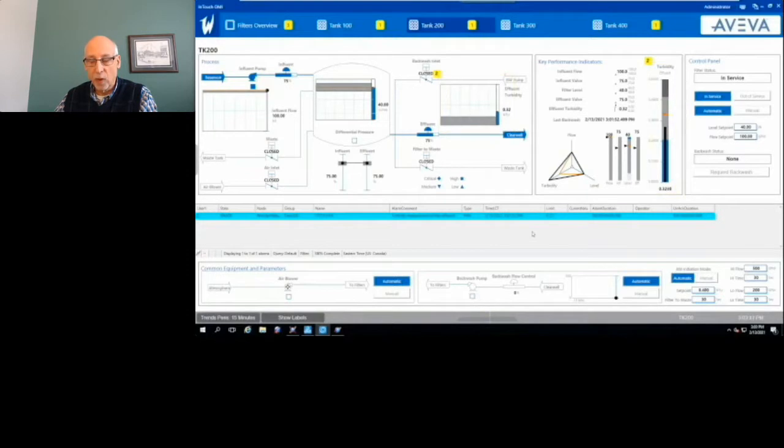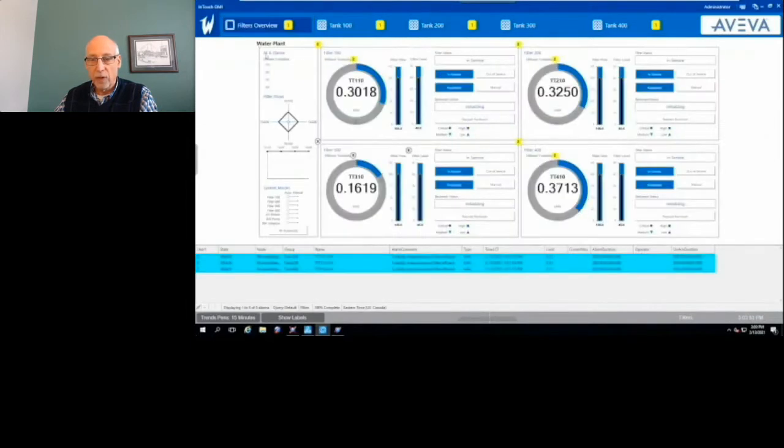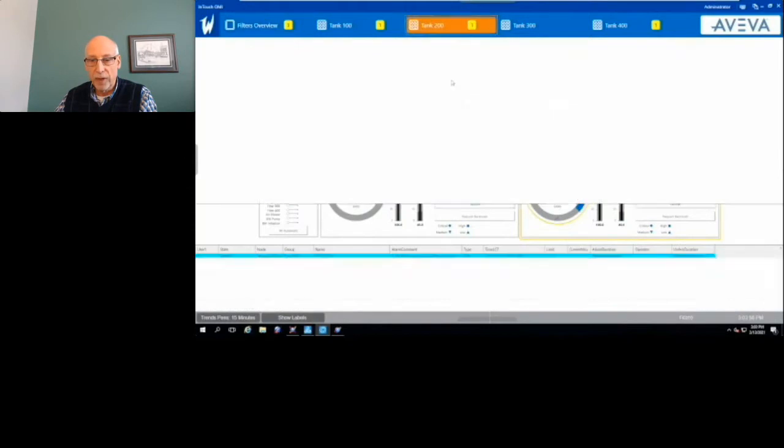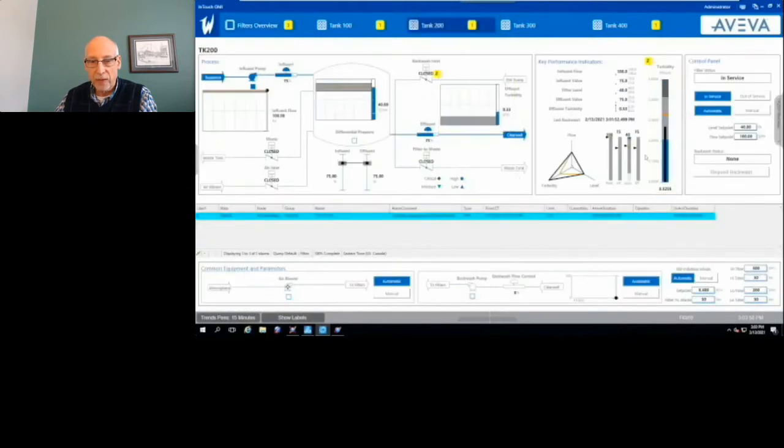One of our demo systems shows that I have an alarm border around my turbidity. It's used to get the operator's attention, so he can see what's going on there. So I'm looking at an overview that also has an alarm border animation. I drill into that, and my turbidity has that alarm border animation around it, that level 2 alarm, to get the operator's attention.